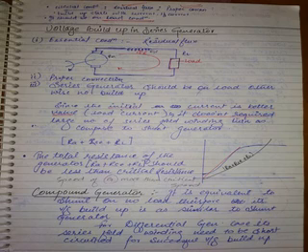Next. You are clearly given the minimum value 8 here. When the field circuit switch is open, you got the minimum value, that is 8, that is residual voltage. You know, if the resistance of the field winding is greater than the critical resistance, what will be the voltage across the machine? It's the residual voltage, a minimum value. So if open is 8, closed is also 8, what will be the result? Same values. What is it representing? It is representing the same thing, 1. So if 1 and 3 are matched, automatically 2 should be matched.